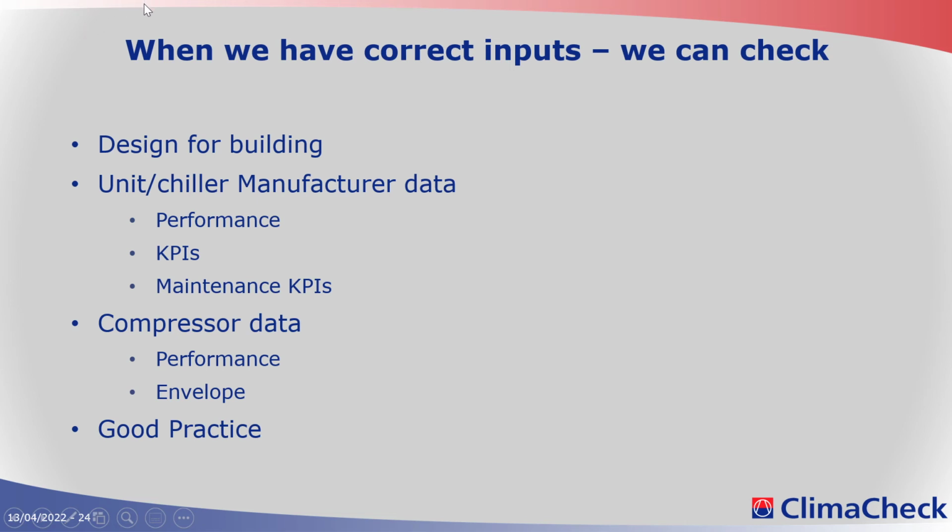So there is a special interest when people make a high investment to verify and benchmark the systems. But in practice, those guidelines in Annex 52 from the International Energy Agency are extremely useful for any measuring and verification in refrigeration, air conditioning, heat pump systems. It doesn't make any difference if we are taking the heat from the air or from the ground. The principles are the same and the measurements we need to do are the same.